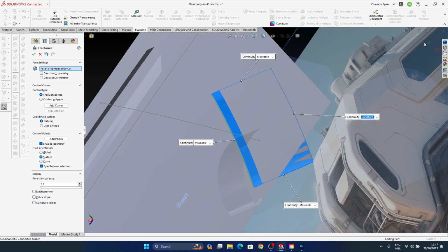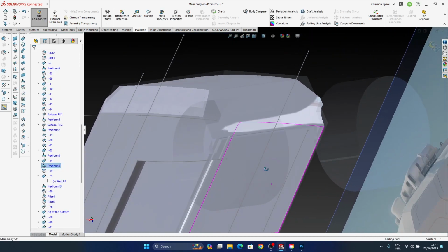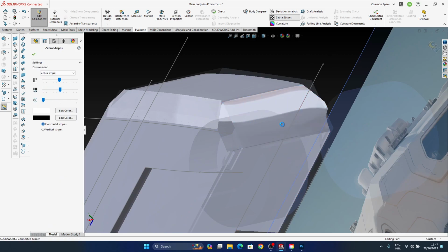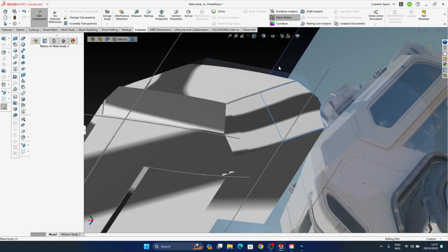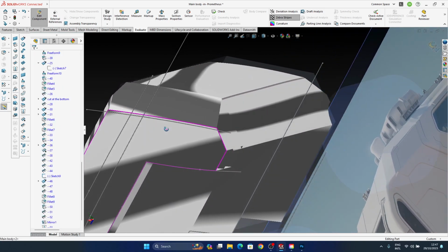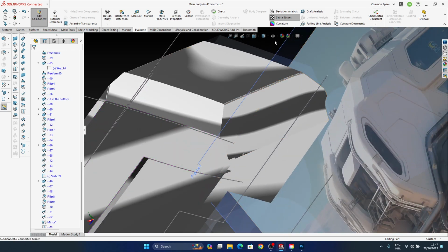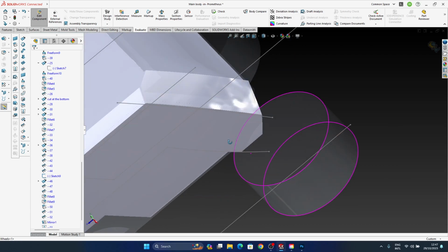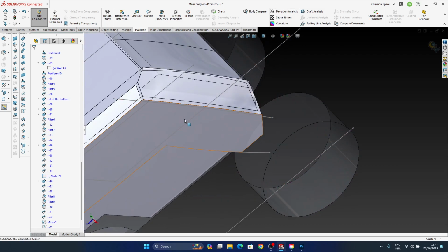So if I'm putting this in curvature now on that side, it should keep everything like before, push down and all that. However, no other lines in here anymore. So if I'm putting the zebra stripes on and deselecting it, yeah, I can see everything is in continuity. So all good, all fine. All right, so now we solved that.